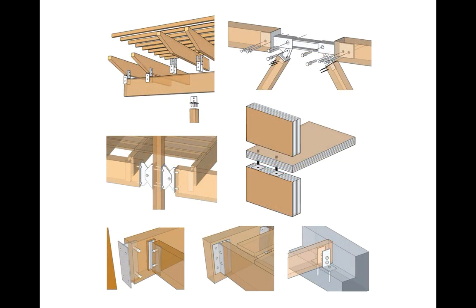And we also use steel very often to connect or to strengthen timber when we're putting pieces together. Because anytime we drive a nail or a spike or a pin through wood, we're not only reducing the capacity, but we're also to some extent damaging the fibers around it. We'll often use steel as a collar to hold on to one piece of wood, to seat it, and to connect it to a piece of wood below. And here you see some fairly typical connections where, in some cases, we're using steel to help put the pin into the wood and to make sure that we're not taking away too much strength from a timber element.